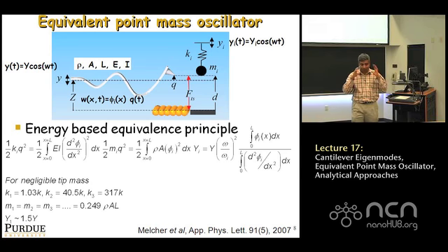Okay, so remember, the concept of the point mass model was based on the fact that the whole beam, I'm going to replace it by a spring of the static spring constant and just allow the mass to be the tip mass, right? Now we realize, look, everything's off. We had to throw all that out of the window because now you have to consider this as a continuous beam with its inertia, everything. So how do we get back to the simplicity of the point mass model? This was very nicely discussed in a paper.